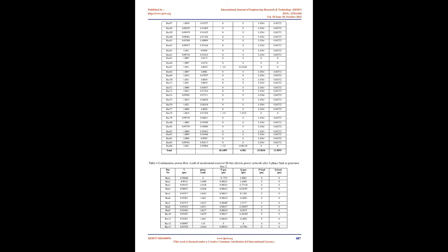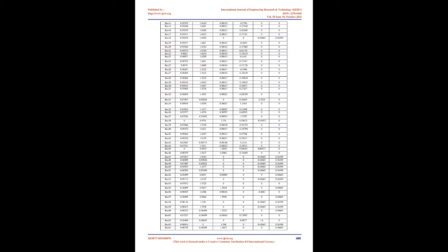Selecting the continuation parameter. The best method of selecting the correct continuation parameter at each step is to select the state variable with the largest tangent vector component. The selected state variable must have the evidence of producing the maximum rate of change near a given solution.